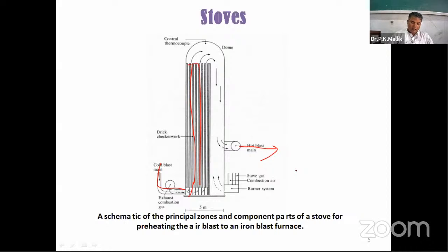Once again, this is an interesting heat transfer problem, and it is posed concerning the optimum recycling time for a batch of stoves. You have to manage how much checkerwork should be there and how much cold air you should supply to the stove so that we can get efficient heat transfer from the checkerwork to the cold blast.